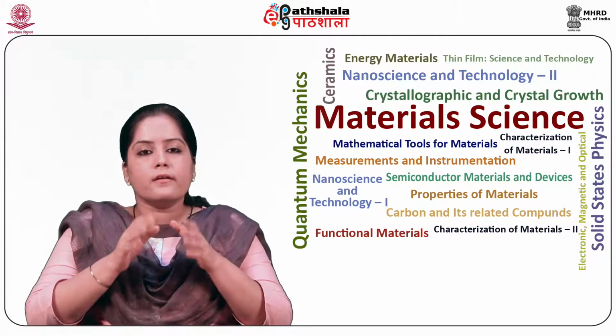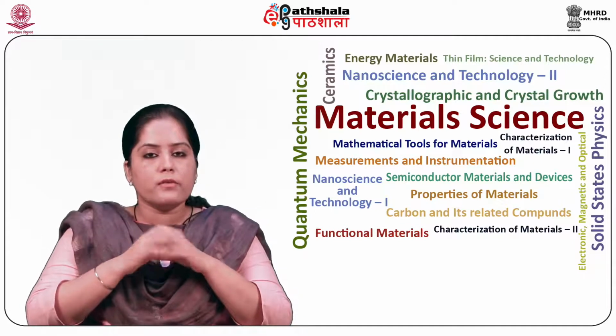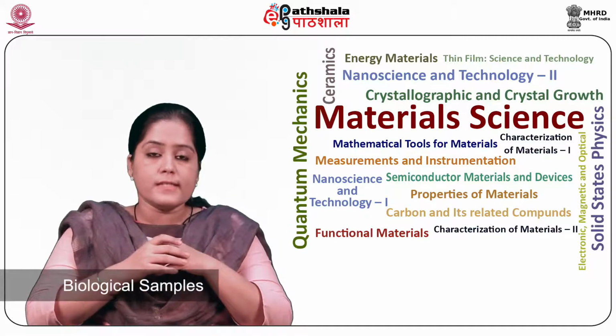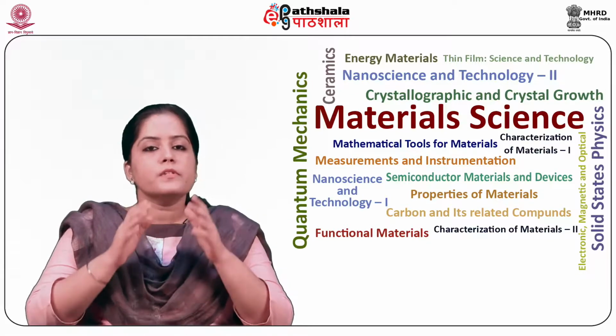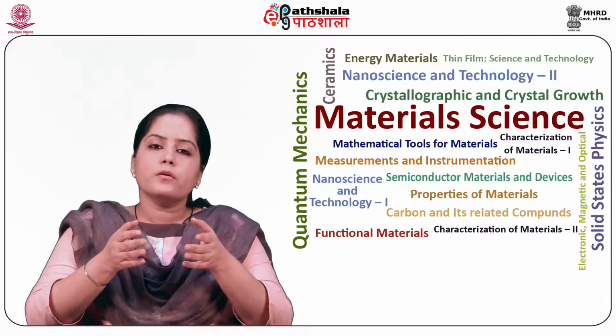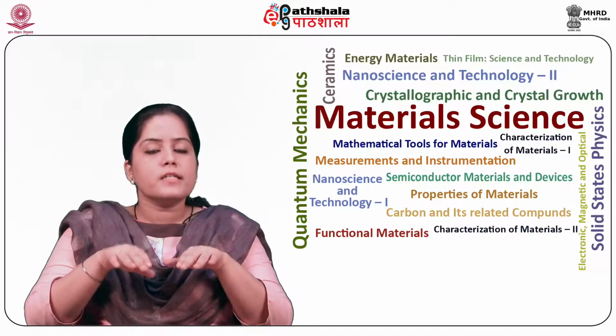ALD is usually run at lower temperatures. The lower temperature is beneficial when working with fragile substrates such as biological samples. Some precursors that are thermally unstable can also be used as long as their decomposition rate is relatively slow.